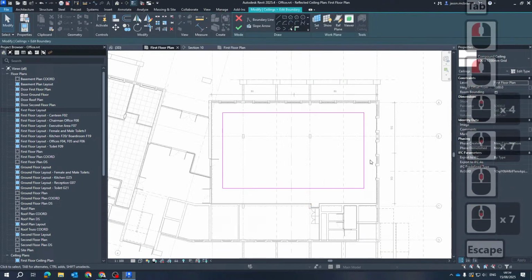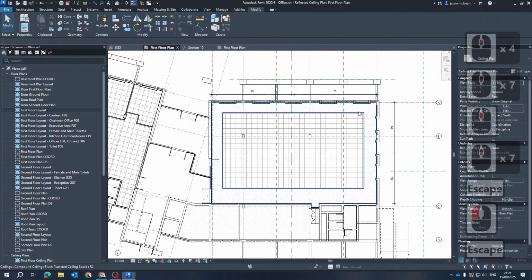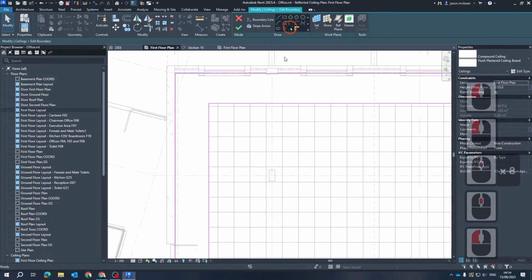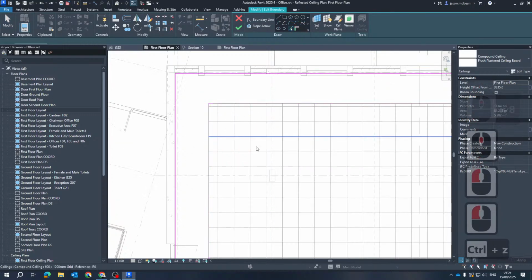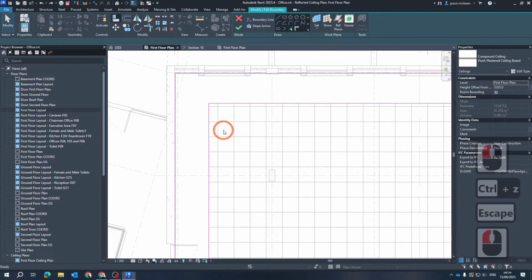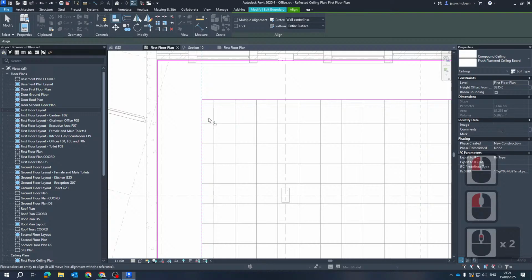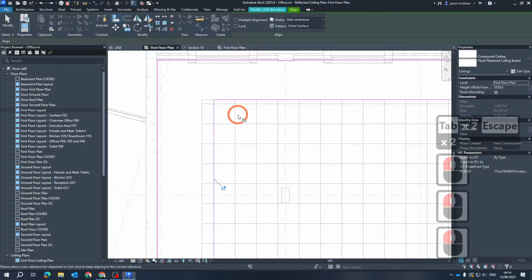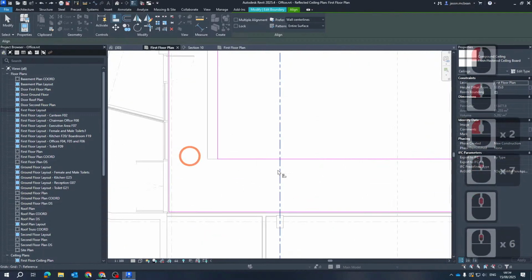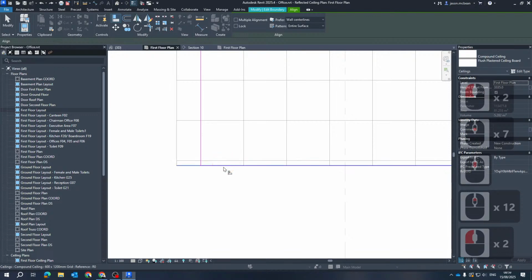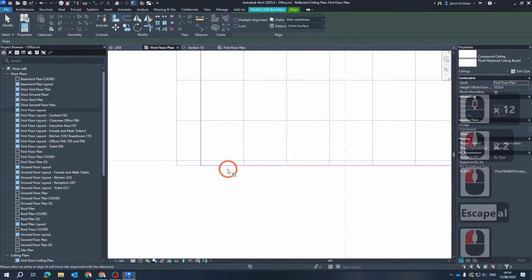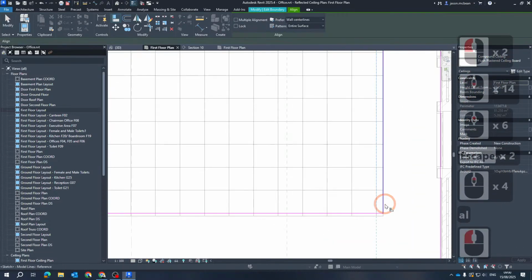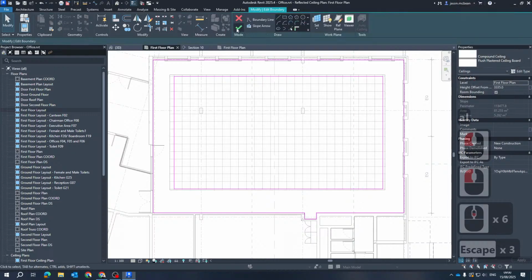Okay, so we need to work out where that's going to happen. I'm going to grab this ceiling first and edit boundary. I'm going to do it in the opposite direction, because I'm going to use the align command. I'm going to align this ceiling to this line over here. So align that, align that. Here we are fine tuning, so align again. I'm using the ceiling grid to help me align how the ceiling is going to work, so the flush plastered ceiling is good. Now that I've established that, I can end the command.